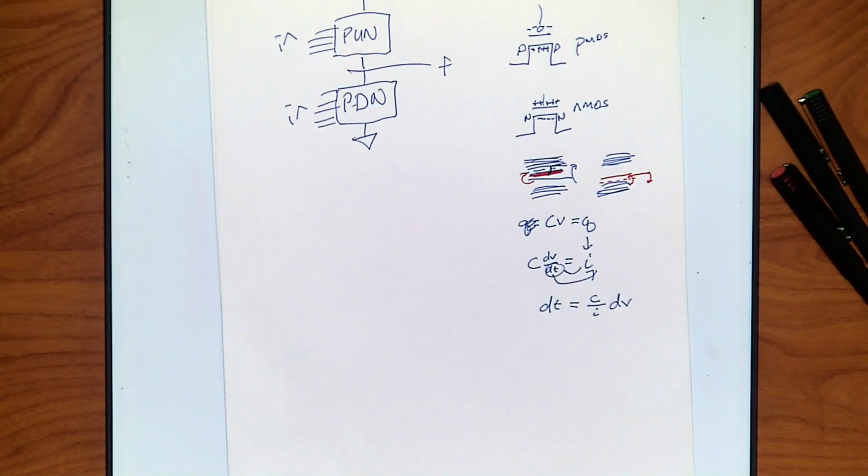This is almost a big totem pole, right? I have transistors on top and transistors on the bottom. I just don't like transistors on top. They're inefficient. So think before the totem pole. Remember how we had the open outs and we had some other alternatives? What did we do to supply power in those? We put in a pull-up resistor. Okay? So could I put a pull-up resistor?